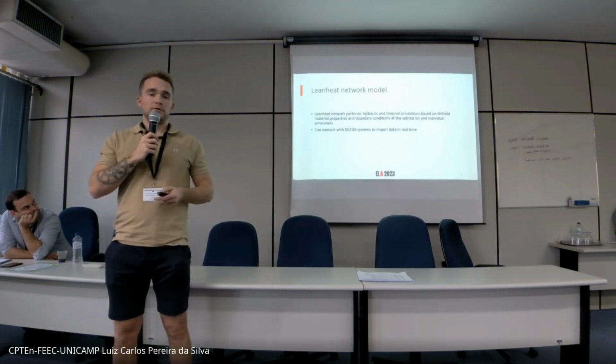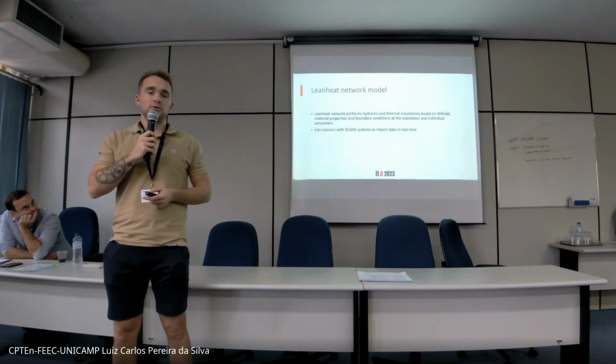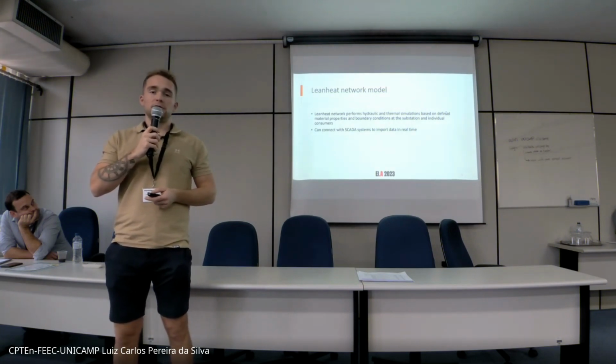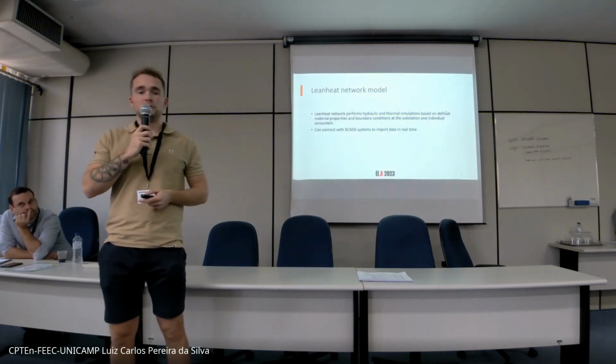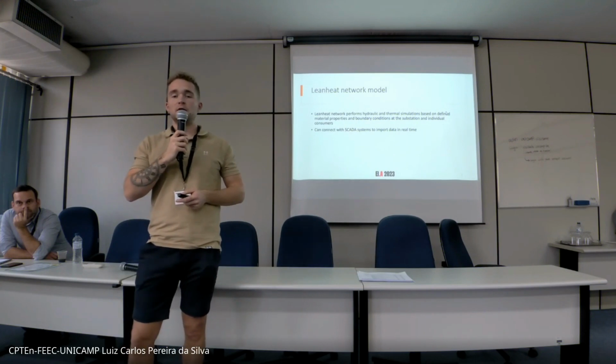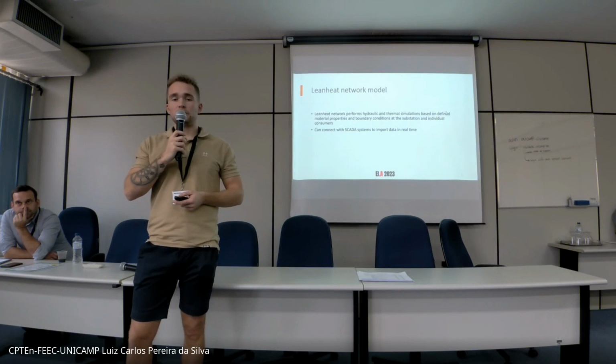The model, as Henrik also touched upon, is developed in a software called Lean Heat Network by Danfoss. It does hydraulic and thermal simulations based on defined material properties and boundary conditions at the substation and the individual consumers. It can connect with SCADA systems to import data in real time and automate calculations.